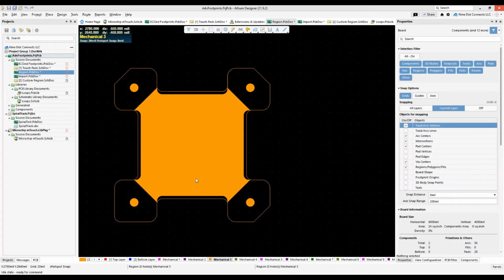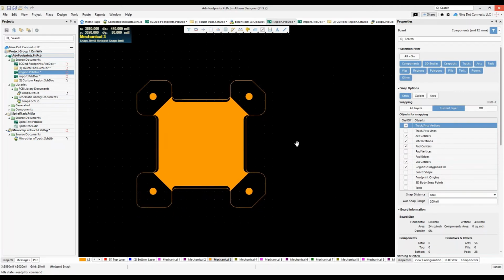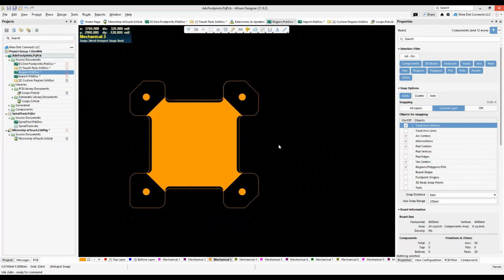And so if I try to put this into my PCB library as is, I'm not going to get any of the benefits of the cutout or any of these other things that could be done within the PCB doc. So what I need to do now is move this onto a copper layer so that the rules will be applied to the polygon pour.